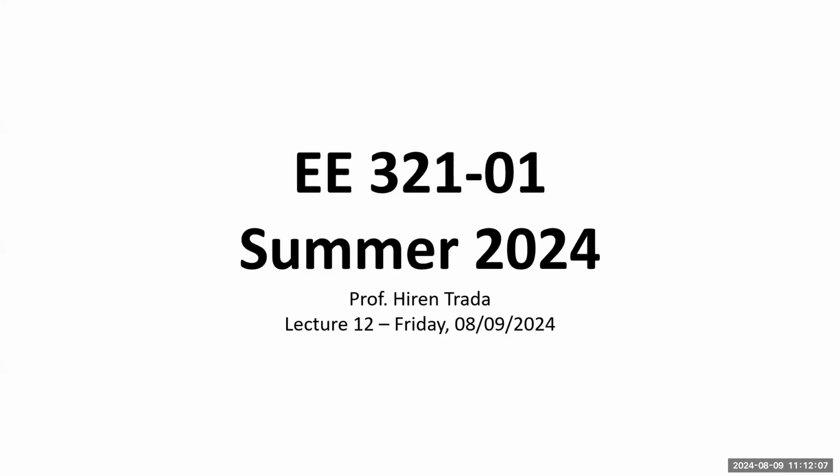Okay, so load line analysis example of a common emitter amplifier. Two more points on what happens when V in of t exceeds the value on either the positive or the negative side. If you remember the modes of operation, we have cutoff, we have saturation, we have active. We bias the transistor such that it should perform in the active region. But depending on the value of V in, it could drive the transistor either to cutoff or to saturation also, because V in of t is going positive as well as negative, right?